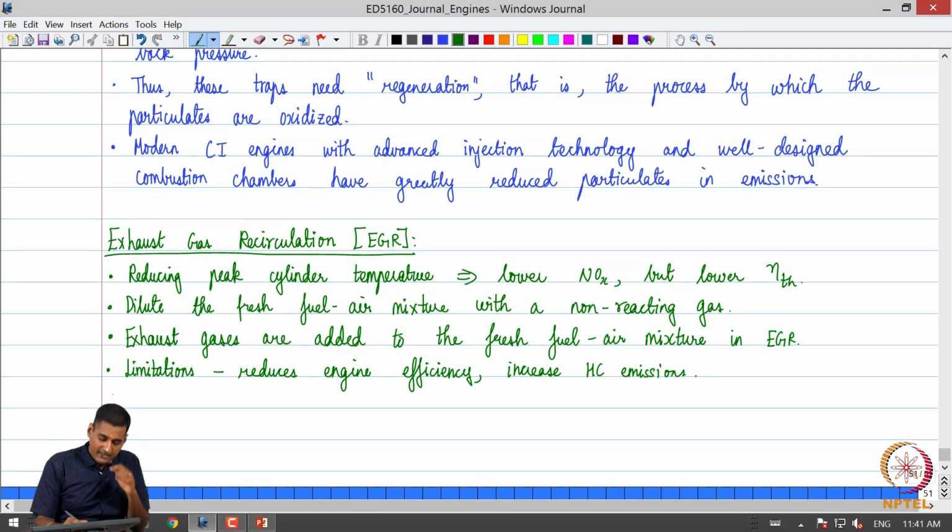emissions, and typically due to this reason, and also based on points that we have already discussed, EGR is typically not used when we want a rich fuel air mixture. What are the conditions under which we want a rich fuel air mixture? The first one is during idling, because during idling anyway the fresh fuel air mixture is diluted by exhaust gases.